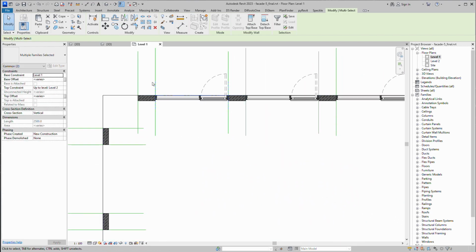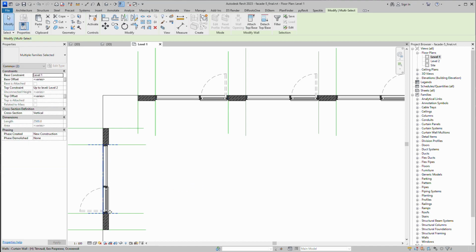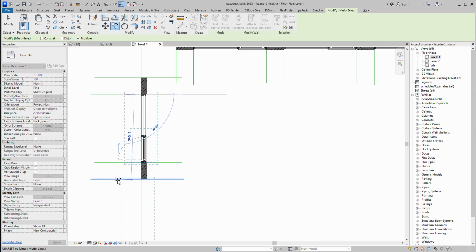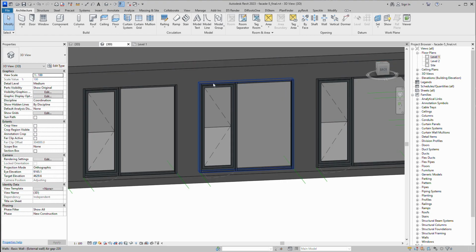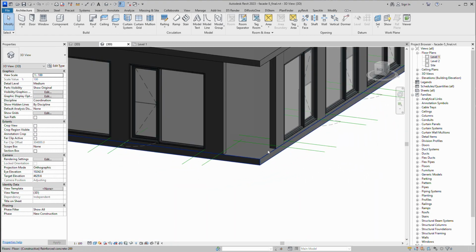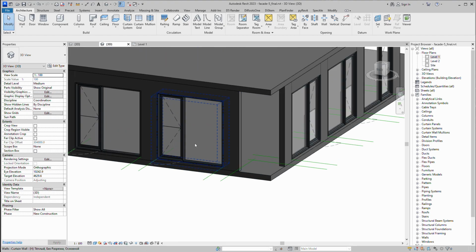You can just use this one to mirror at 45 degrees, and it will be exactly here. After that, you can copy from this line to this line and this line to this line. Let's go to the 3D view, and as you can see, everywhere we have the windows. Okay, awesome. So it's possible to create your own window, for example, without openings.